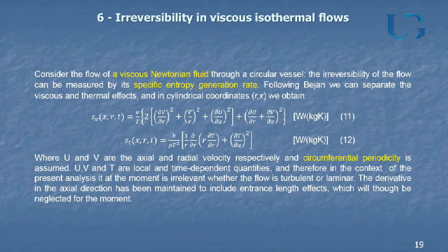We saw that yesterday, entropy generation. Why am I interested in entropy generation? Because the entropy generation multiplied by T0 gives you what is called the Gouy-Stodola lost work. It's the work lost in irreversibilities. So it's a work lost in inefficiencies of the system.